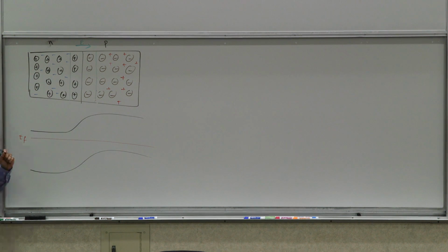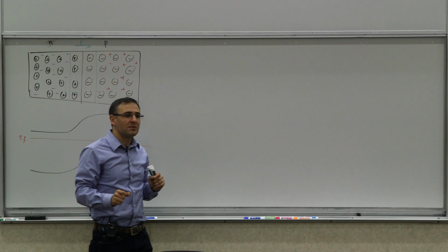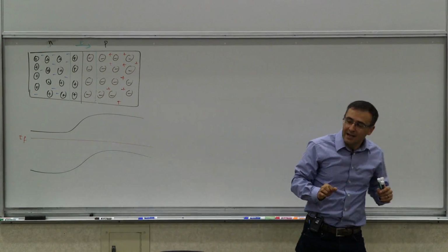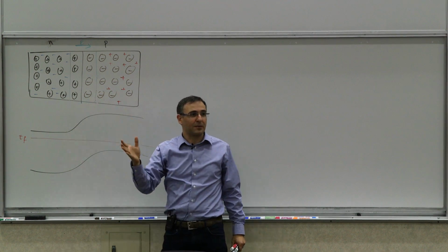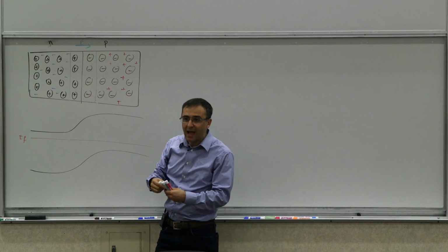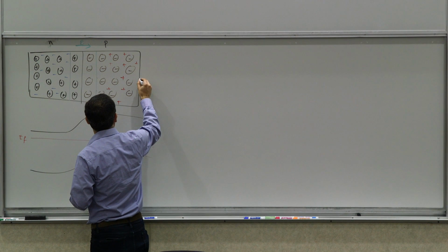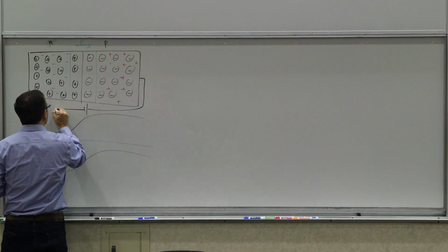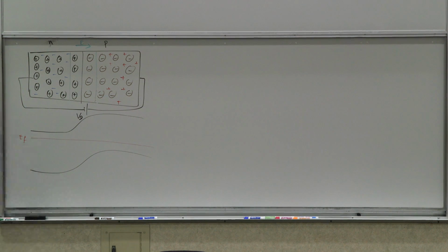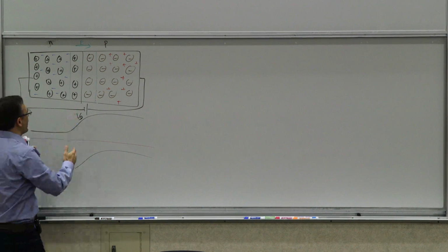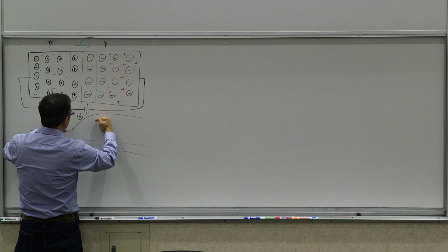And of course, again, I want to emphasize the difference between thermal equilibrium and steady state. Now, if you leave it like that, if you don't connect it to anything else, it's in thermal equilibrium. Now, one of the things we did was to make this diode forward biased, right? When you apply a forward bias, there will be current flowing. We saw that the current is exponentially dependent on this V diode. And the way it happens is that you're lowering this potential barrier.